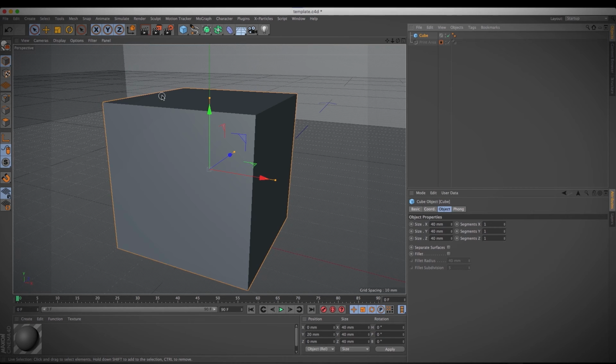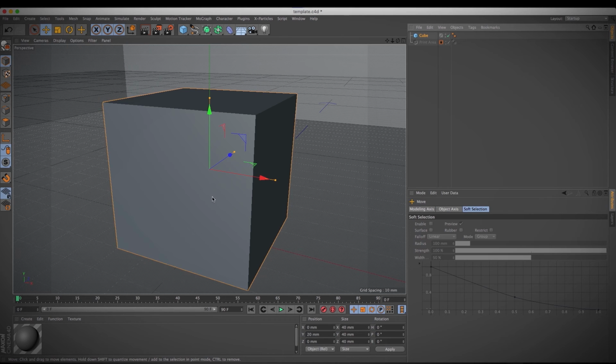To move the cube object around, we'll use the first set of tools in the toolbar at the top here. But we'll use the shortcut keys to access those functions. First is the Move tool. By tapping the E key on your keyboard, that will bring up the world movement handles on the cube on the stage. These are color-coded to help you define which axis you want to move the object. If you mouse over an arrowed handle on the object on the stage, the color will turn white when you're using that axis, like so.